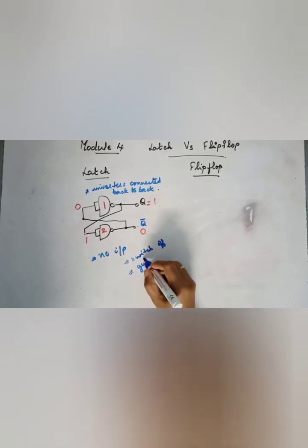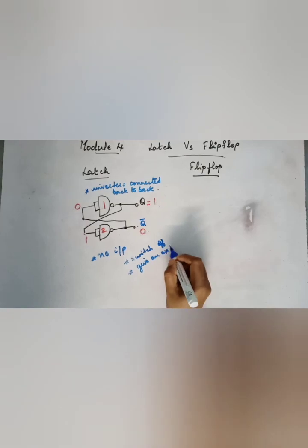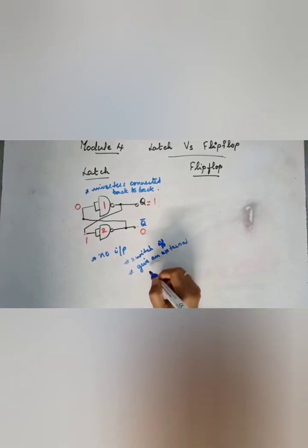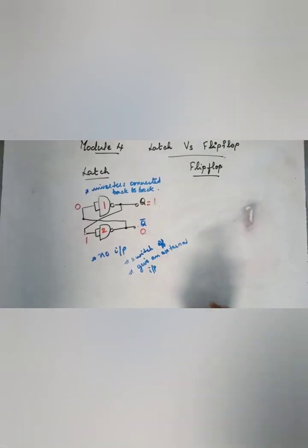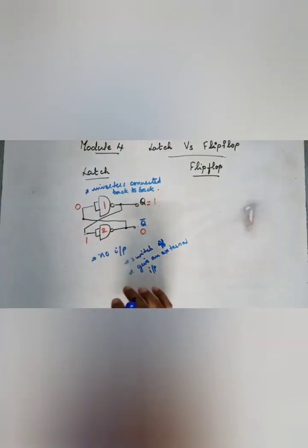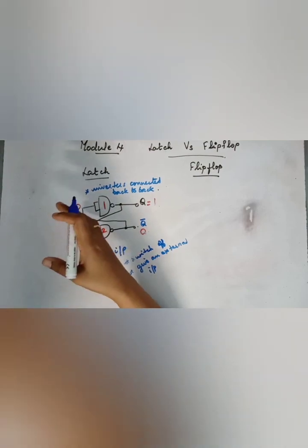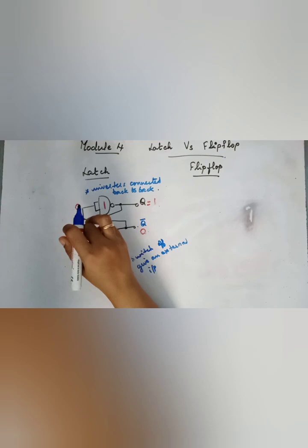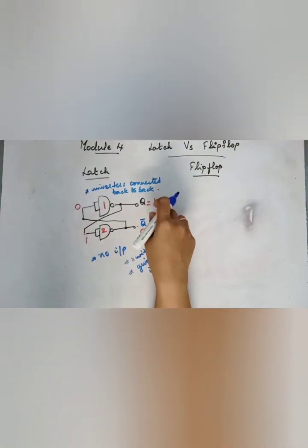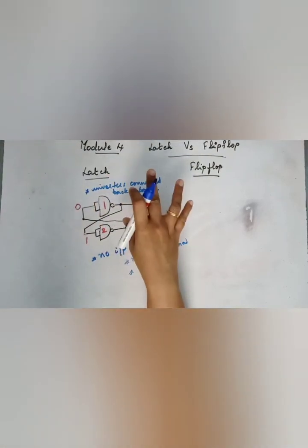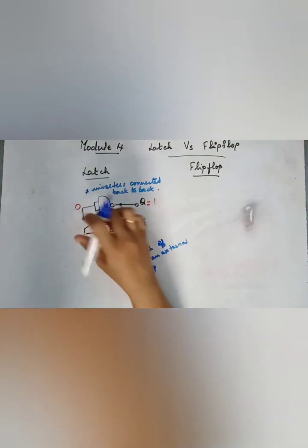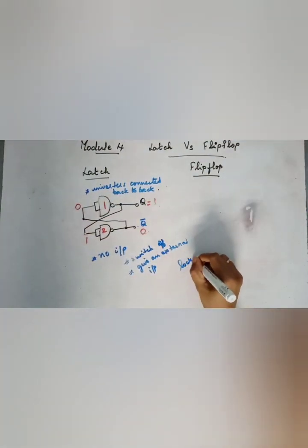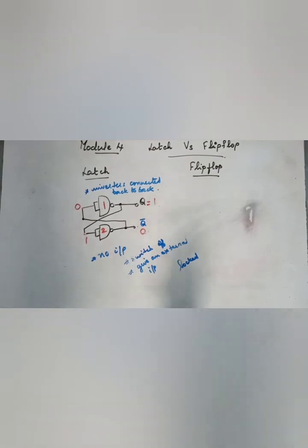So until you switch off the circuit or give an external input, force an input, because you don't actually have an input provision. But if by any means you are forcing an input to one of these NAND gates, then you can change the output. Otherwise, this is locked to the state in which it is while switching on the circuit.